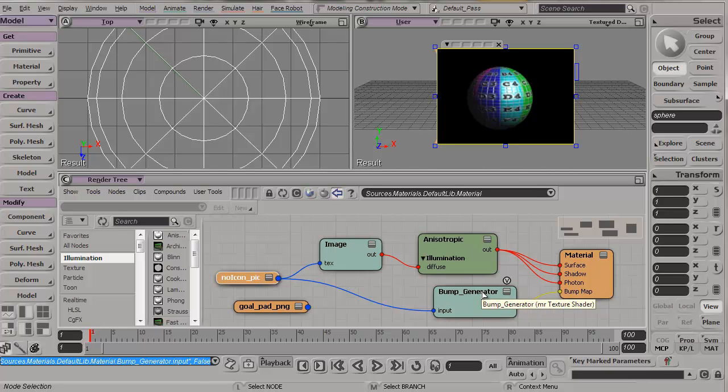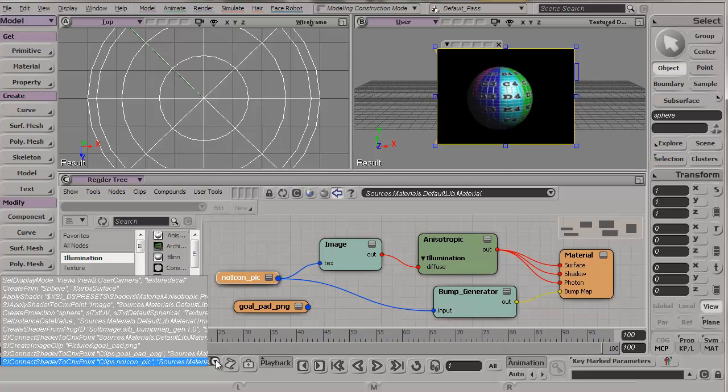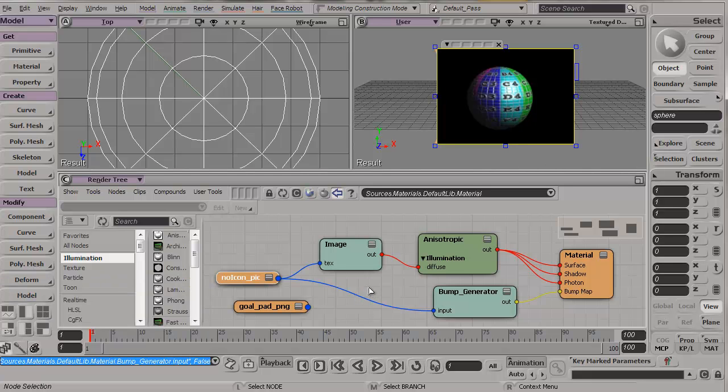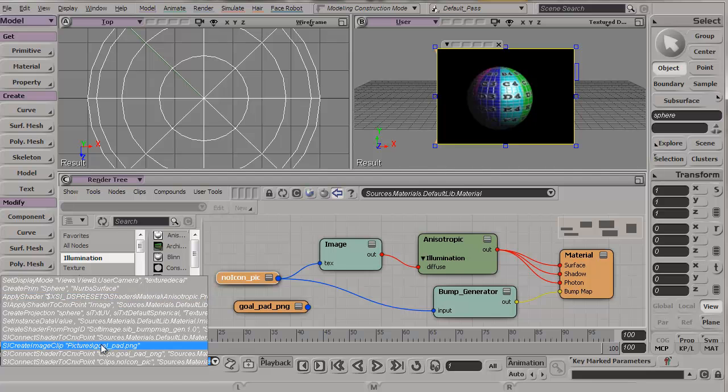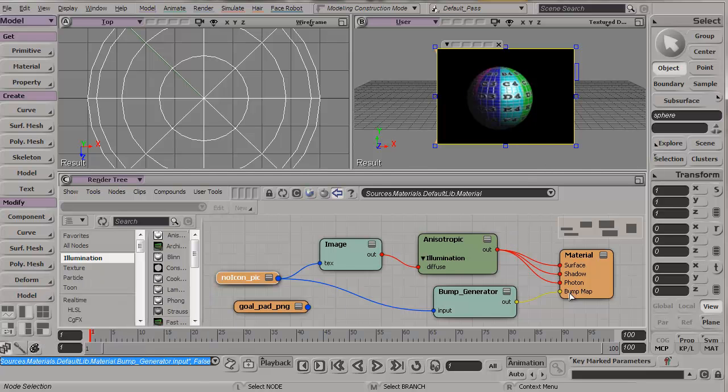So this is an example of programming, scripting, and it's entirely iconic, and I'm being informed about what inputs and outputs I can use based upon this system. Now I can see over here that all of these things that I just executed are actual commands being done in C# within the interface, so that these things actually happen to the model. So this iconic drag and drop schematic node-based editing format is actually creating command calls that are being utilized within my application.